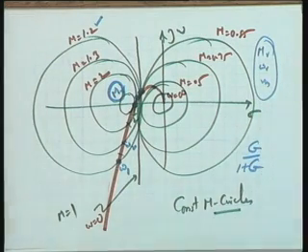If this point has been well taken, can you tell me from this very plot, how do I get the bandwidth of the system? Bandwidth also is a closed loop frequency response characteristic. Intersection with M equal to 0.7. That is fine. I think it is very clear.